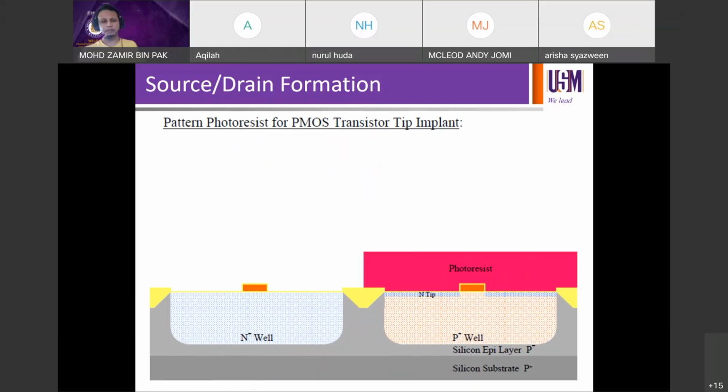So it really depends on what you have to have on the device, okay? It doesn't necessarily have to be a fixed flow because it really depends on what you want to fabricate. So in this case, if you're talking about positive resist, you have to pattern on the right, and to be able to pattern on the right, you have to expose on the left, okay? Expose on the left, reverse process that you discussed.